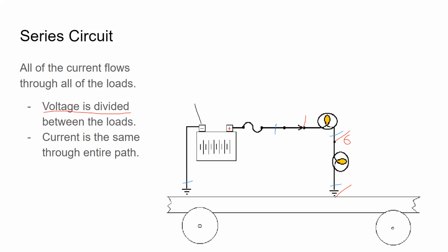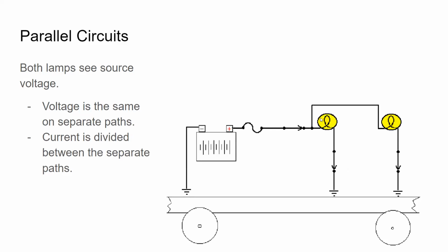Now, something that can happen on a series circuit like this, if you've ever messed with Christmas bulb lights, if you've had one bulb in the strand go out, both of these bulbs would blank out. If we have a parallel circuit and I interrupt either one of these switches, if I disconnect this switch right here, and we'll just pretend that that doesn't exist anymore, I've opened this switch, I've affected this one light bulb, and this one bulb would turn off, but the other bulb would keep going just fine.